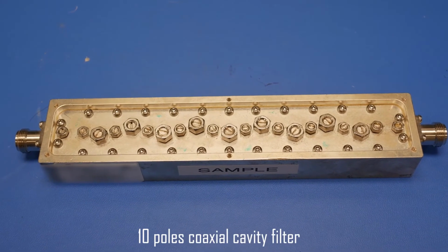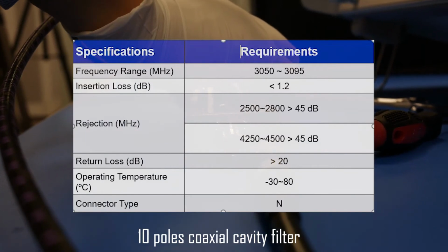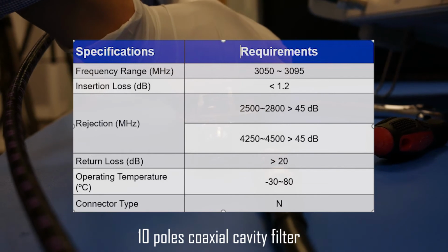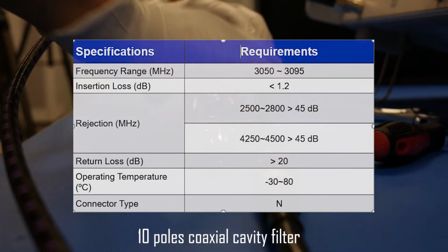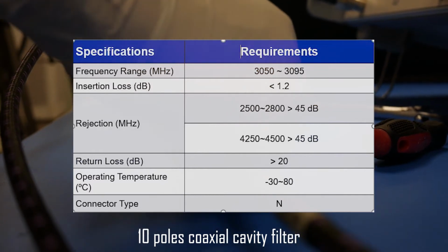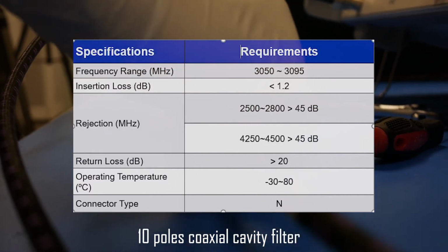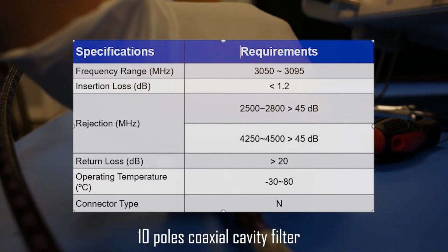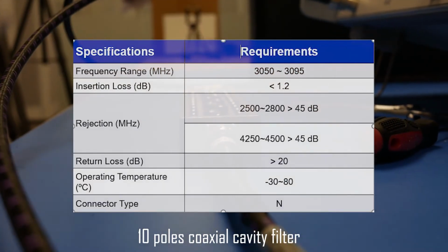The central frequency is 3.5 GHz with 1 GHz design bandwidth. So we have a 30% fractional bandwidth. No doubt this is a wide-band application. Outside the band edge, about 205 MHz from each band edge side, it has 40 dB rejection levels.